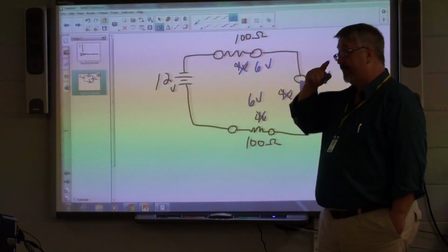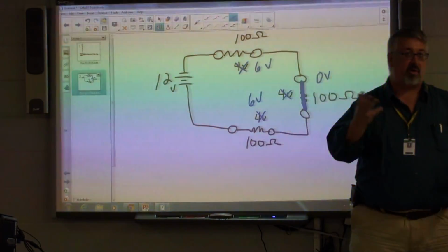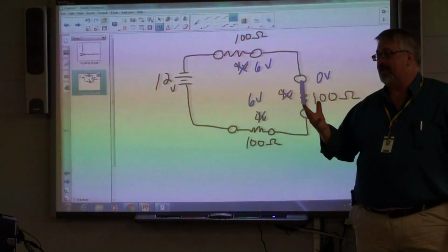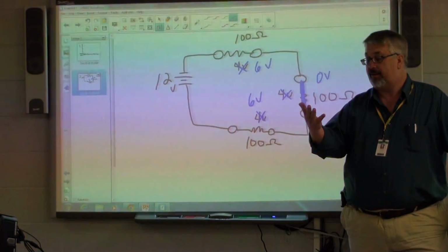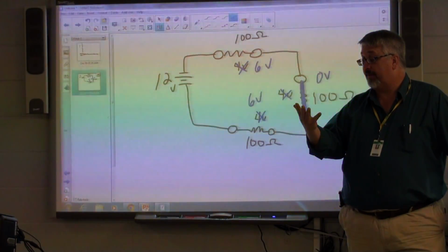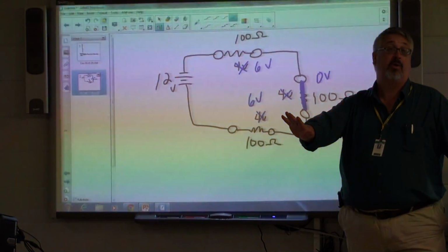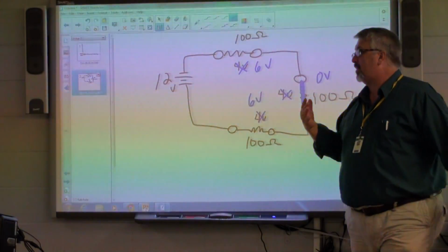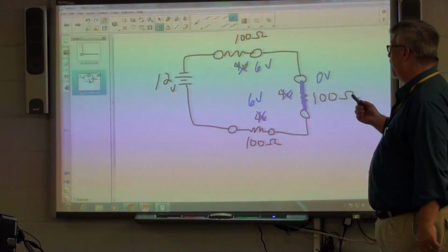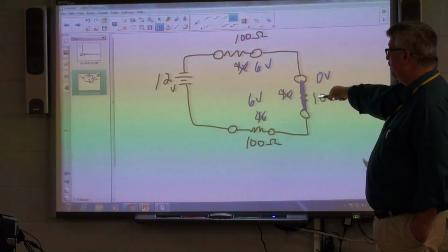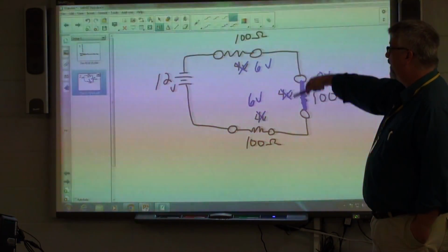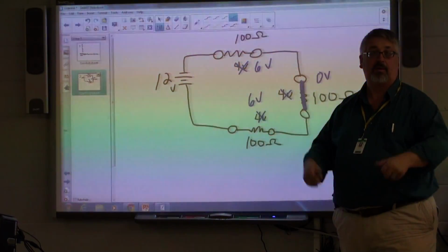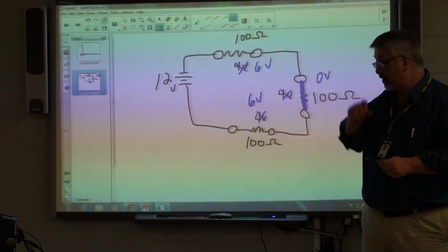So what can happen in the field, especially if you were working on a component level board, is the resistors may visually be there, and you go, well, no, R1, R2, and R3 are there, and then you turn it over and go, I get it. There's a short on the back. So that's what effectively happens, is we read no volts across here, but these voltages, which would normally be 4, are suddenly shot up to 6.